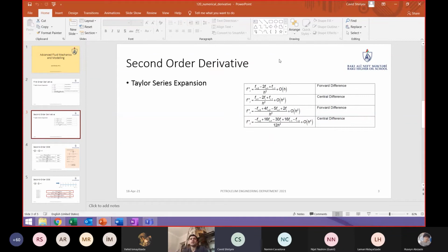That's the main difference between the implicit and explicit solutions, and that's the main reason why explicit solutions are not robust, and they can diverge in scenarios when we don't have proper grid sizes. But an implicit solution most of the time converges with any given grid sizes. Now that's one important term for simulators, implicit or explicit solvers. We are going to show why implicit solvers are better, and we are going to continue mostly with the implicit solvers.